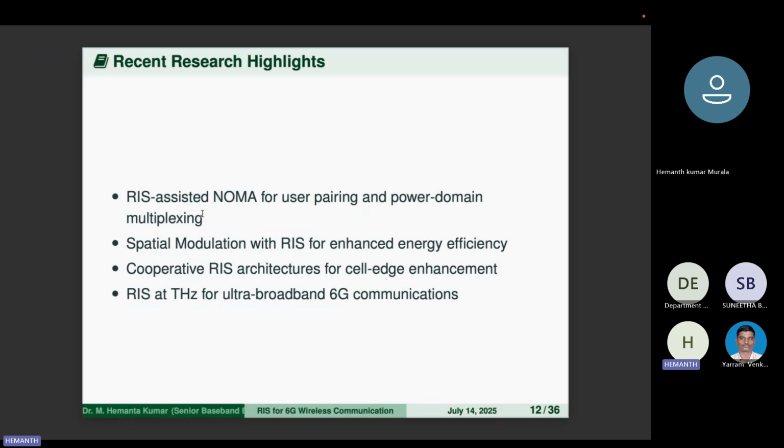Okay. So the first concept is clear. For 6G you are going, then you have to prepare a better SNR. Better SNR you will ensure by using IRS. But what about massive connectivity? Connectivity also you have to enhance. Then how will we enhance that? So we go for another scheme, that is NOMA, non-orthogonal multiple access. Okay? If you combine IRS and NOMA, then the rate will be satisfied as well as connectivity.